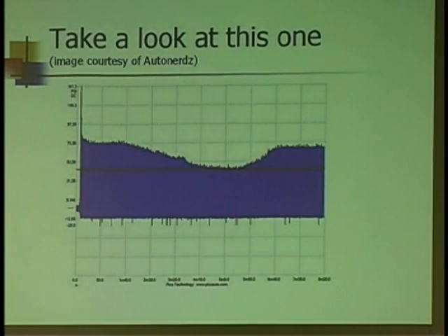Here's an example, too, of how this can be used. We kept talking about intermittent sealing issues. Now, this particular capture has 8 minutes worth of data on it. One screen. Another thing I like about the scope, I can set a trigger to look for a problem, turn the scope on, start the car up, and then go do something else, because I've given the scope the parameters of when to start drawing. Okay? And on some of the PC-based, even the handheld devices, you can store a lot of information at one time that you can go back and look at later.